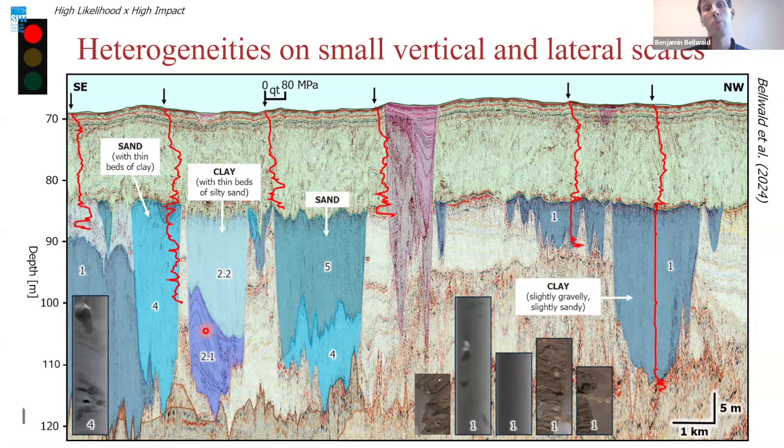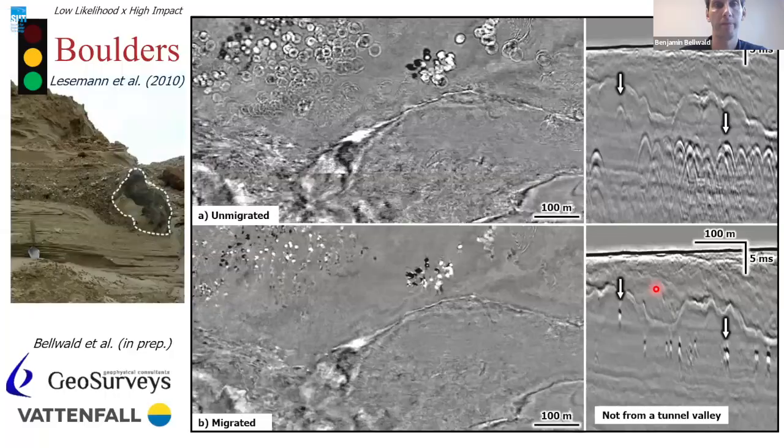So really complex, and it highlights the use for spatial control of the infill, and where we may have some flank collapses like here, or more some sandy outwash like here, and then this one may have been covered, filled in by a lake. So it's really key to integrate all existing high resolution data, geotechnical data, geological data, to make the most robust ground model for your offshore wind farm, or also when you're just making a foundation principle for, let's say, an oil and gas platform.